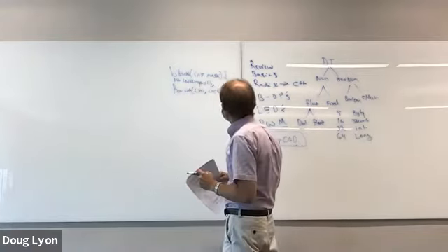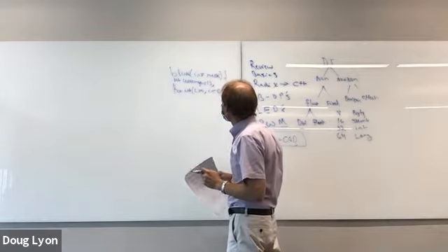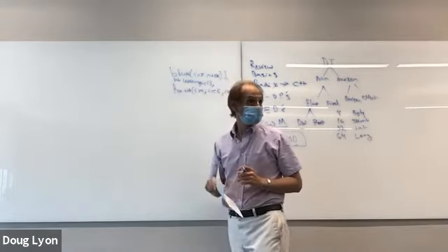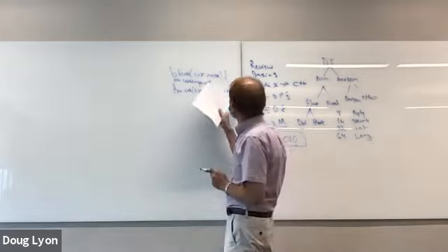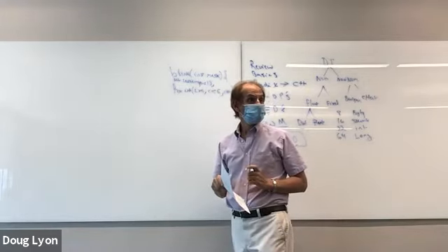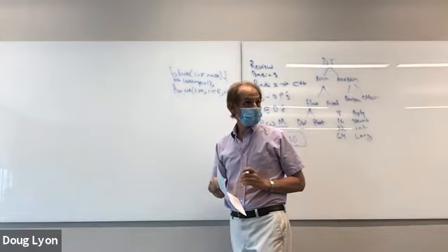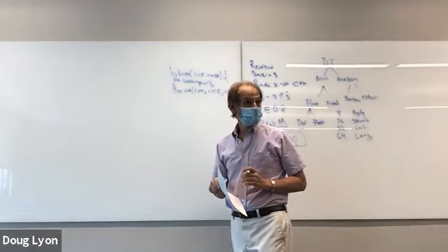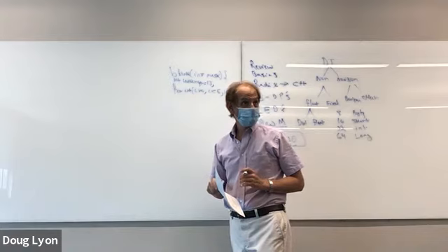So now what we'll do is figure out what LED 13 is going to be. We'll look at the least significant bit. If it's a 1, LED 13 is on. If it's a 0, LED 13 is off.